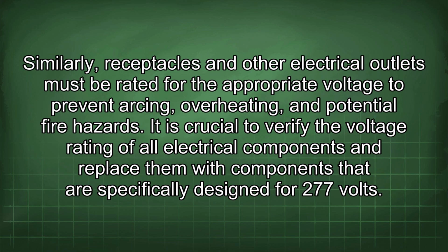Similarly, receptacles and other electrical outlets must be rated for the appropriate voltage to prevent arcing, overheating, and potential fire hazards. It is crucial to verify the voltage rating of all electrical components and replace them with components that are specifically designed for 277 volts.